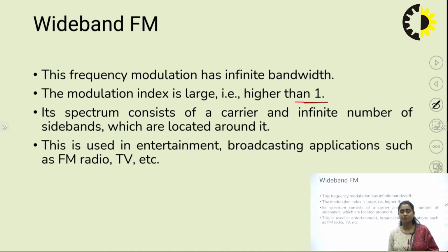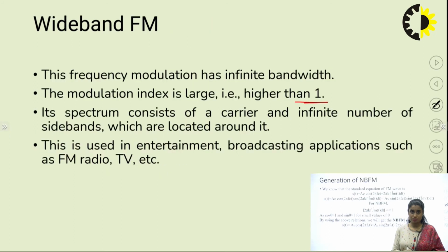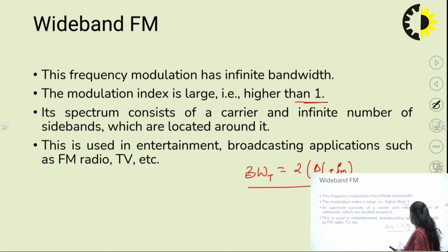But the actual FM, that is your wideband FM, has infinite bandwidth. Bandwidth expands to infinite. Although communicating using infinite bandwidth sounds somewhat impractical, so we have a rule for it: Carson's rule, which we discussed in the previous lecture. As per that, we limit the infinite bandwidth to some measurable amount. I would rather term it the transmission bandwidth, which equals twice del f plus twice fm. This is the transmission bandwidth of FM, right?